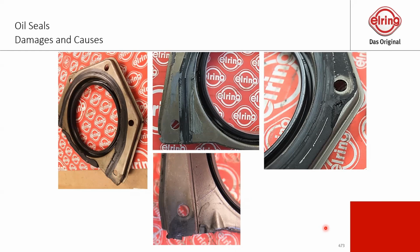The other big question is all the time how you remove oil seals. There are a lot of techniques out in the world, from putting a screw into the oil seal and then going with the pliers and pulling it out, or going with a screwdriver, whatever. So there are a lot of solutions, which is a classical way to remove oil seals. But in the end, oftentimes there's a problem that you maybe will destroy the shaft, the oil seal or the housing.